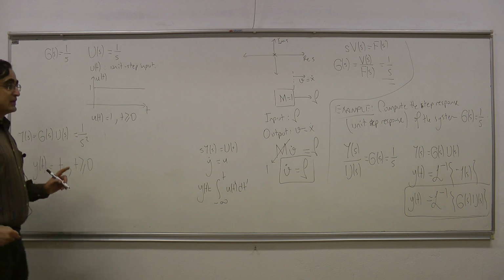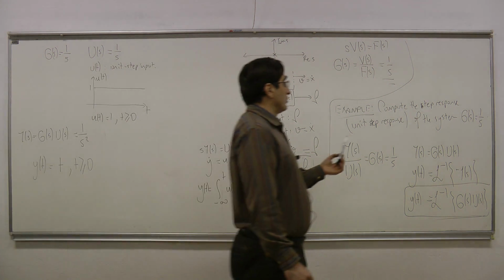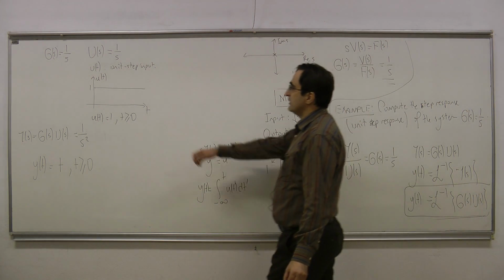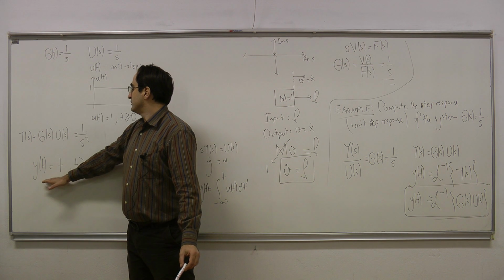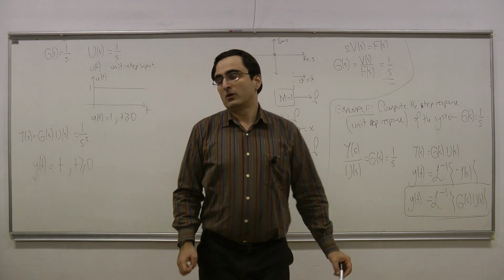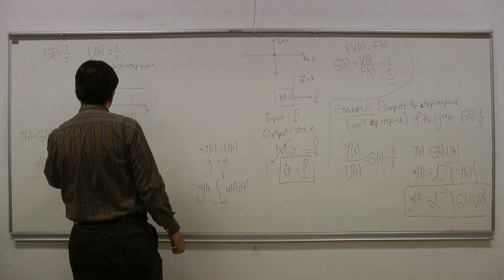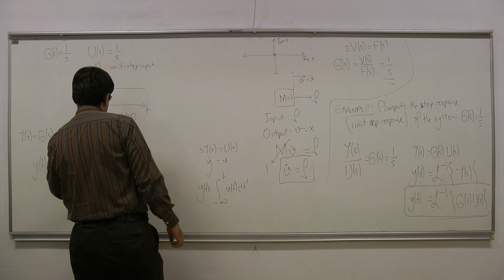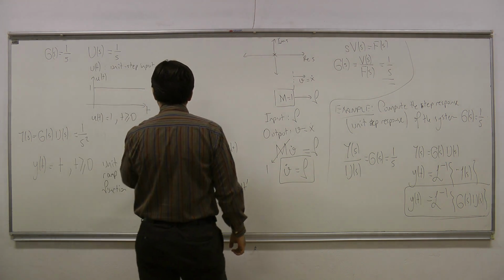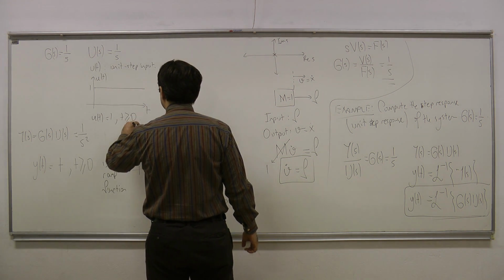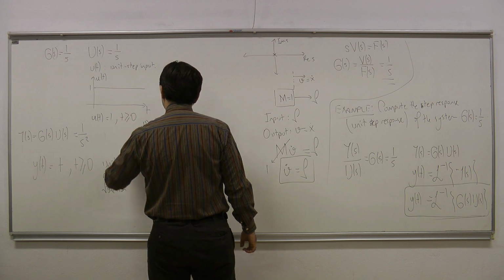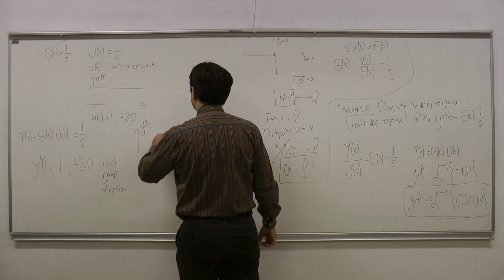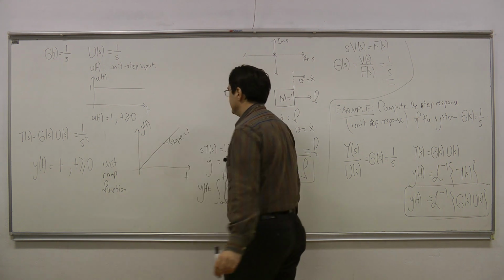This means that the unit step response of the system that we are considering, which is the integrator, is the unit ramp function. So this is defined as the unit ramp function. If I try to draw it, you might remember this from earlier: I have y of t, and it is just like this, and the slope here is 1.